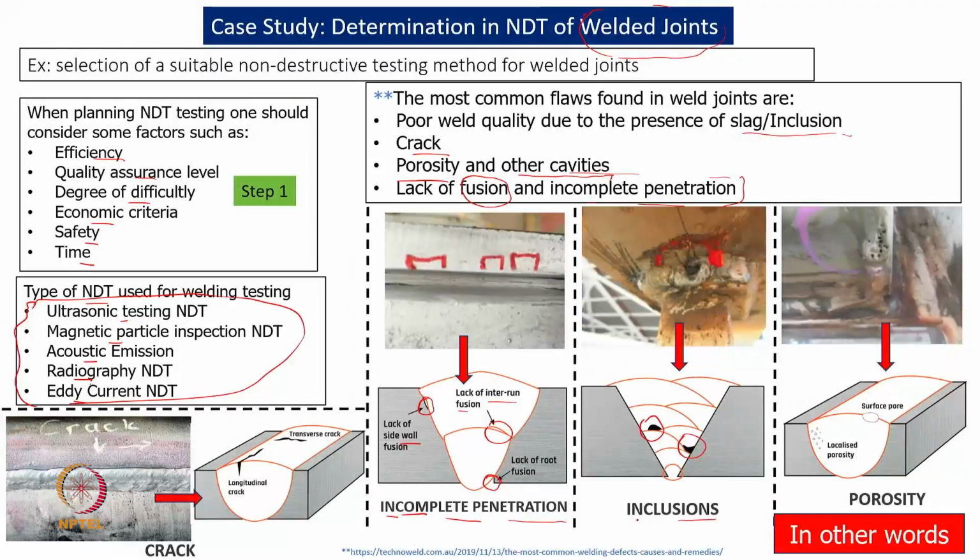So, that is why we say inclusions are another possibility. Now, you are able to see here the gas bubbles, small gas particles. It can happen subsurface, and it can also happen on the surface during the solidification. So, porosity is another possibility of defect, and it really happens. One of the worst things is delamination.